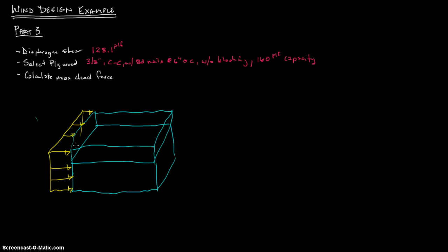That is the wind force we're looking for. It's a pounds per square foot on that plane right there, and it actually got a little bit bigger there, but I'm not going to worry about that right now. We already have the rest of it. I'm going to get rid of this. So where are we at? We've gotten the distribution of that load, and we turn it into a line load coming into that diaphragm. And that is the 128.1 PLF.